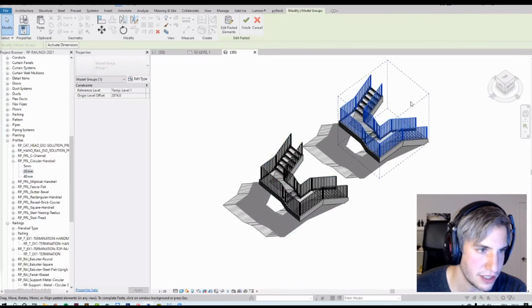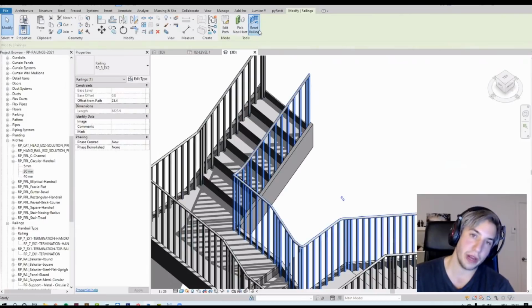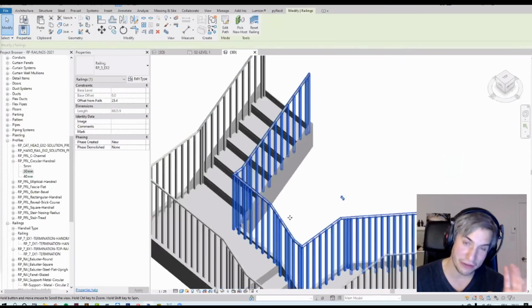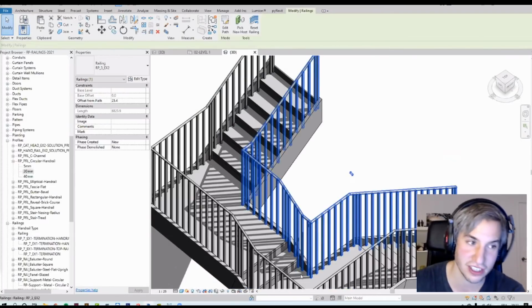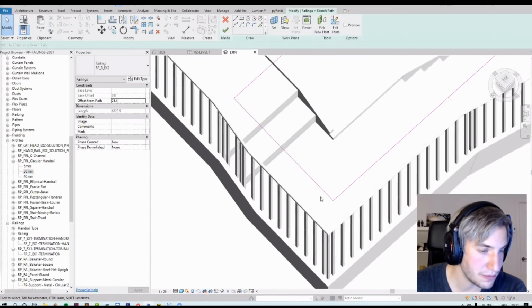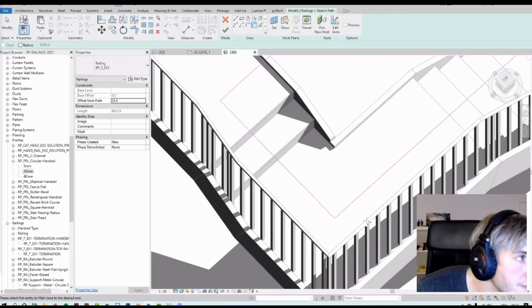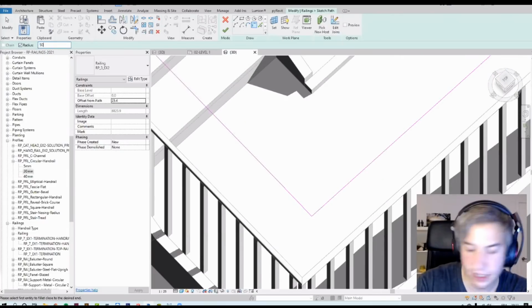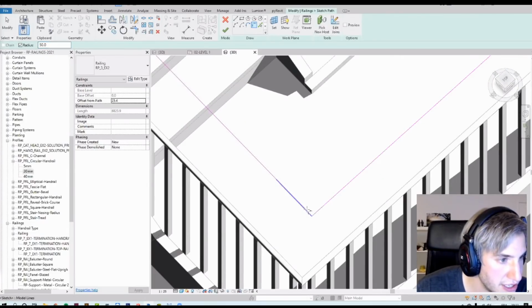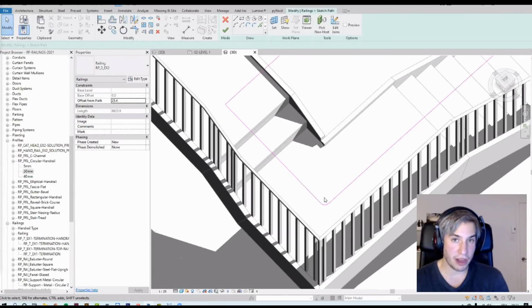So I'm going to copy the stairs. Another little tip: you can click on reset railing. It's going to go back to default. You have to be careful with that though. If you worked all the little transitions, it's going to mess you up. But let's say here I'm going to create a fillet value directly. Where is the fillet tool? There it is. Okay, radius. I'm going to set let's say 50. I click on the two lines. So I put it directly on the railing path, on the purple boundary lines of the railing.